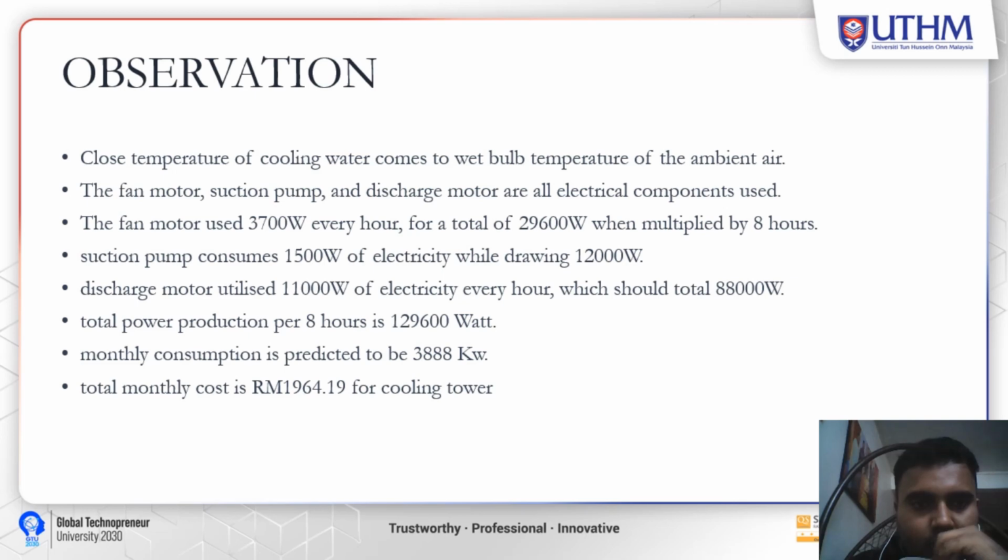So, the heat transfer phenomena in the cooling tower water. The performance of a wet cooling tower is measured in terms of its approach, which is how close the temperature of the cooling water comes to the wet bulb temperature of the ambient air when the water is cooled through the desired range.